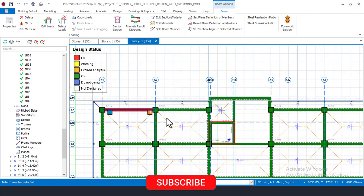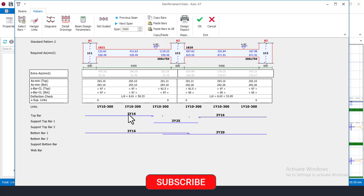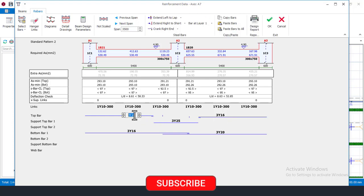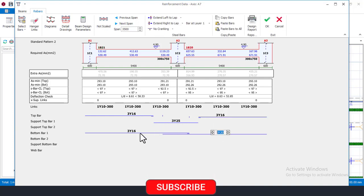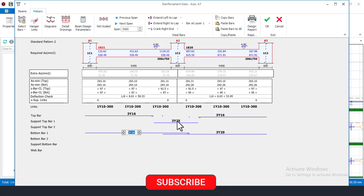And then I will now come again right now, and you can see that these bars right now are not well arranged. At the top here, we'll have 3Y16 here, 3Y25 at the support, and 16 again here, Y20 and all that. This will cause confusion at site. During the construction, it will cause confusion and it will bring so many off-cuts. So instead of that, I'll try to treat this top here to use just one bar diameter. So I'll have to convert this 25 diameter to at least Y16 or 20 if I can do that.